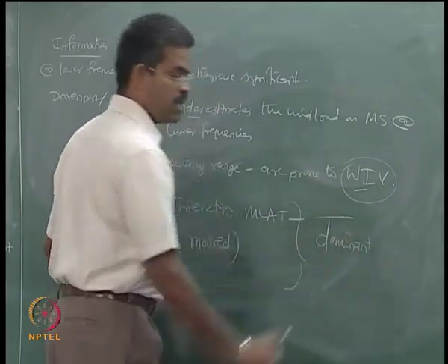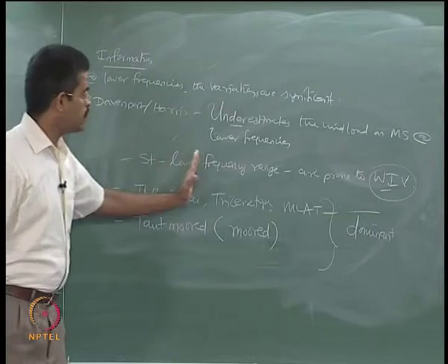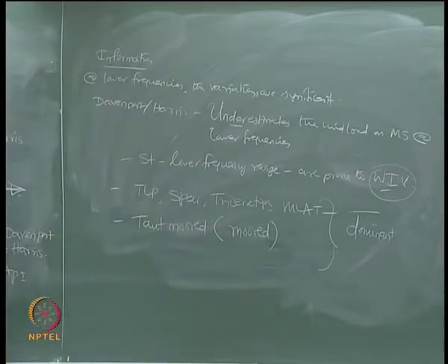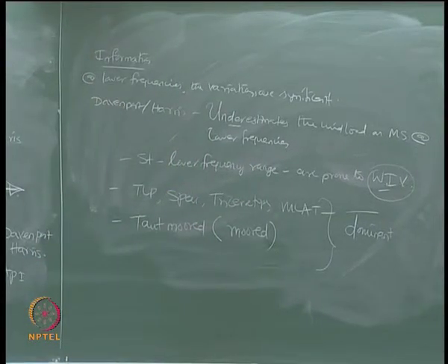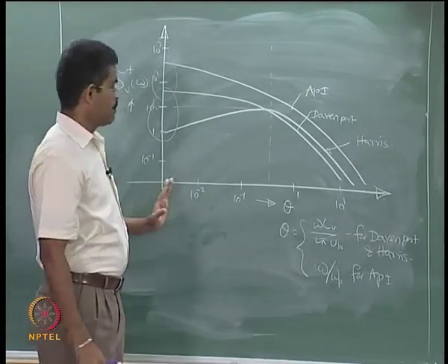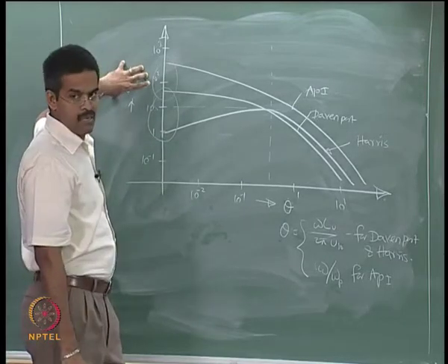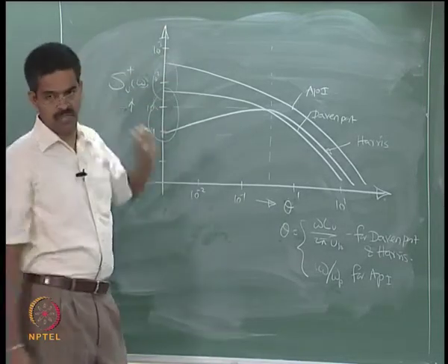So, it is necessary that I must compute the wind loads on these structures, which have a lower frequency band, in an appropriate manner, because if you compare the classical spectra available in the literature at lower frequency bands, the variations of the spectral ordinate are significantly different.